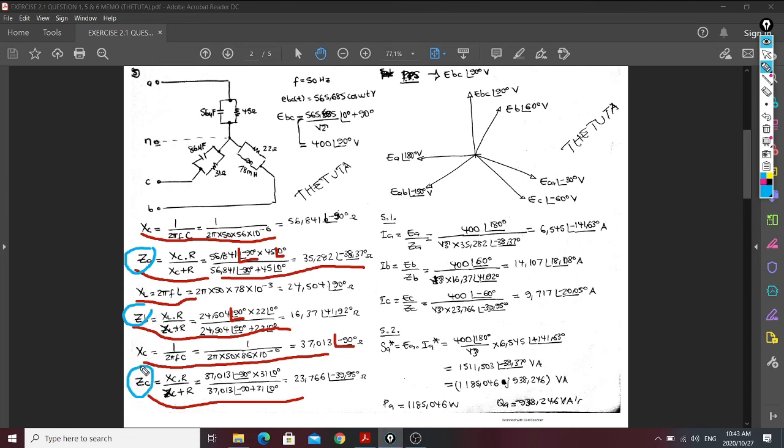So in this case, they give us the loads in the form of components. You need to get the total impedance first in each phase. Another thing you observe is that they give us a cos here, which was our reference voltage. With the cos we always have to add 90 degrees, because our supply is always a sine wave, and we divide it by square root of 2 because it's an instantaneous value. We change it to RMS, therefore we're going to have this to be our EBC.